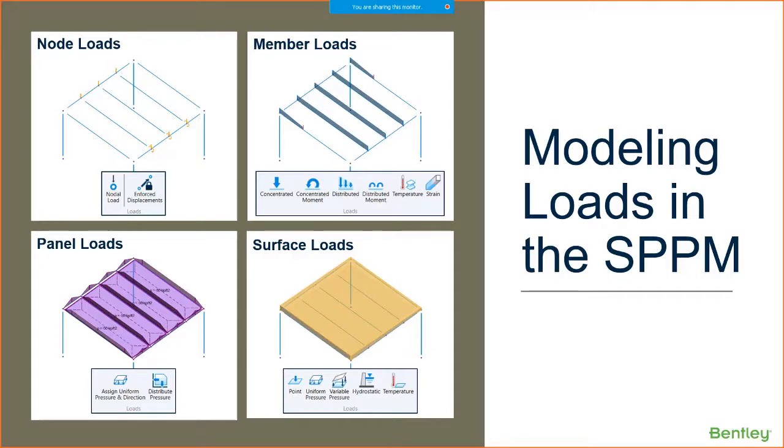The new type of system that you might not be as familiar with, but it is available in the physical modeler, is basically panel loads. Now, when you create a panel within the physical modeler, you're not creating any type of structural entity that's adding any stiffness or any weight itself to the system. No self-weight will be associated with a panel load. It's just a way for you to create a surface load and have the model automatically distribute it to the supporting members. So you're basically going to add a panel within a bay, and then that load is going to be distributed.